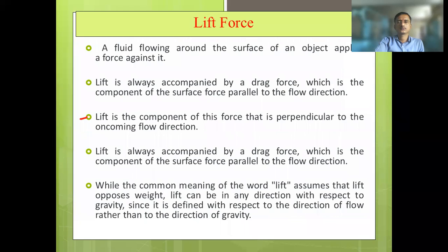So let us understand about the lift here. I have told you that this lift is always acting in normal direction to the direction of motion. So if the direction of motion is here, if the object is like this and it's moving in this direction, then the lift will be in normal direction to the direction of flow. Lift is always accompanied by drag force, which is the component of the surface force parallel to the flow direction.